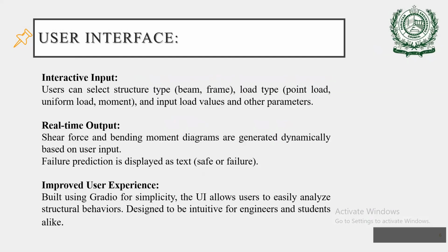So this is the user interface. Interactive input: the user can select structure type, beam or frame, load type, point load or uniform load, and can input the load value and other parameters like frame width and frame height. The real-time output is a shear force and bending moment diagram, generated based on our user input.